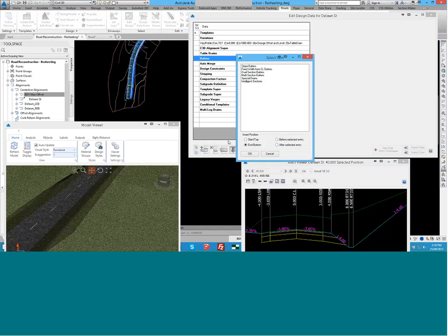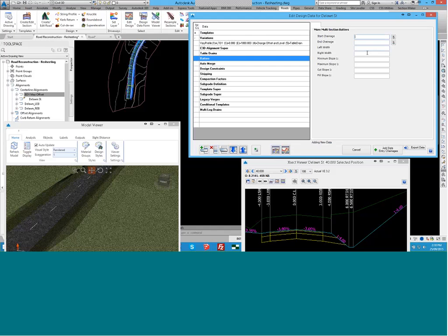I am trying to move through these fundamental things a bit quicker so I can get to the more conditional stuff. Now, the next one I wanted to show you was the dual section batters. So remember, this is the one where, similar to a fixed width, because I define a width, but if the slope to the surface or slope of the batter is outside a range of slopes that I pick, then a second leg will be inserted. So let's have a go at this. I'll insert this one for the whole length.